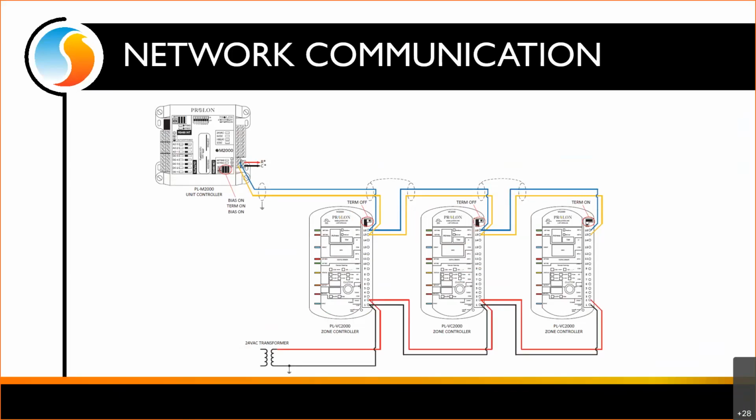So the zones can be saying, hey, we're using a lot of heat here, or hey, we've got a high cooling demand, and then the rooftop can relay that through a math function to the boiler or chiller controller, whatever's appropriate there, as far as increasing the water temperature or decreasing the water temperature, whatever we need to do.